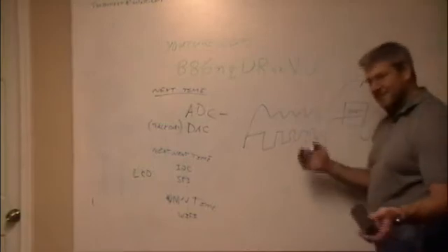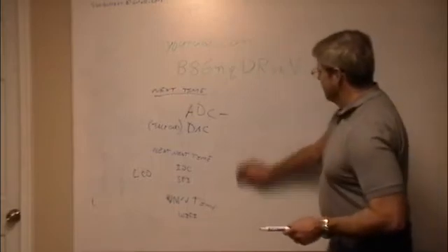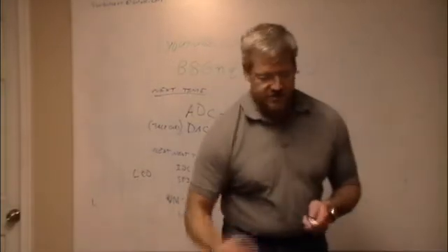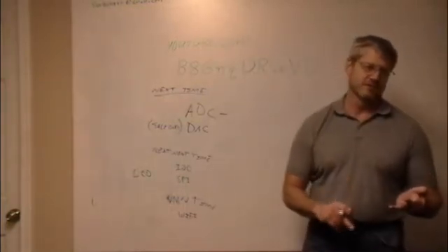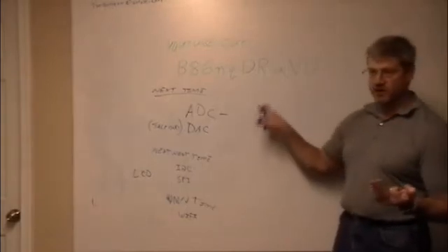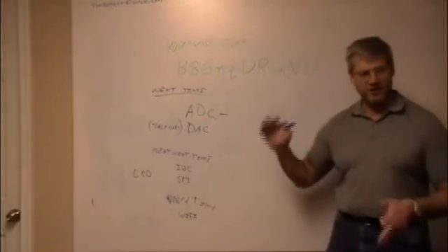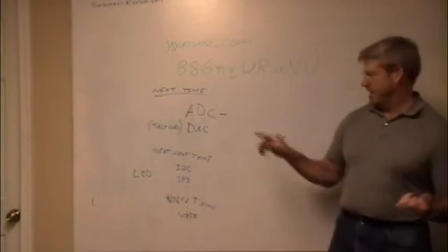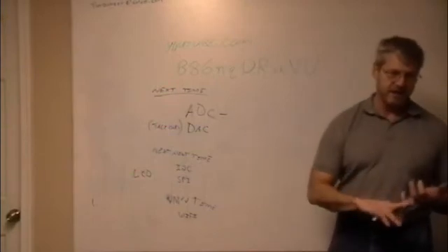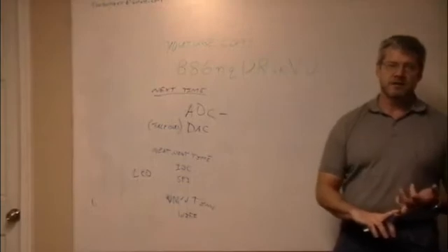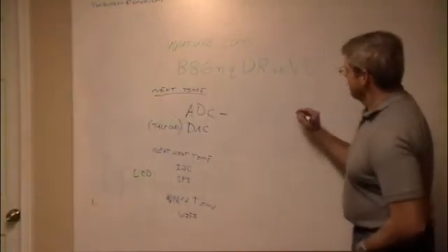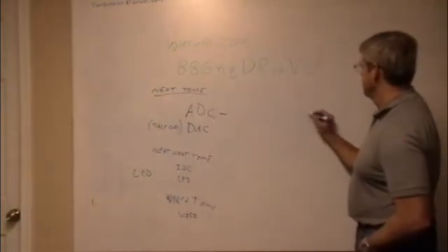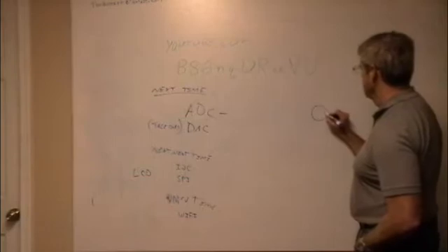I think on the 3D printer, do they call it PID? The kind of predictive. PID is a PID loop. PID loop is proportional integral differential. So purely proportional is this bang bang, on off, on off, on off. Now you add in an integral term, and we're going to get into control law here real quick. But that would probably be overkill for what he's trying to do.